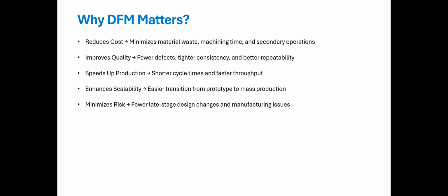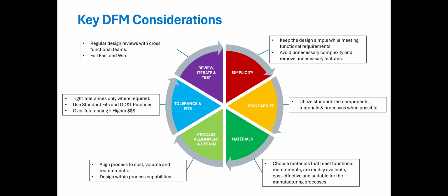All right. So when applying DFM to any product or design, there are a number of considerations. First, when it comes to design itself, you want to try to keep it as simple as possible while being able to meet the functional requirements. That means avoid unnecessary complexity and remove any unnecessary features. If it's not needed, it's just wasted space, which most of the time just results in additional costs.